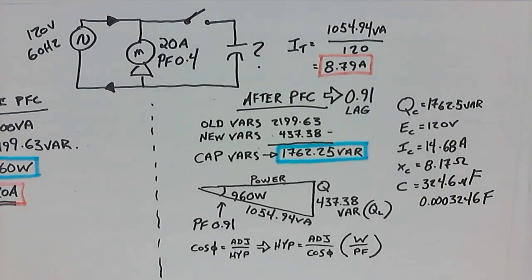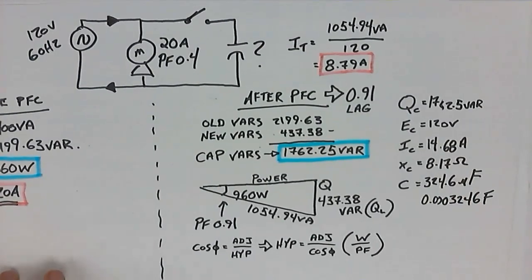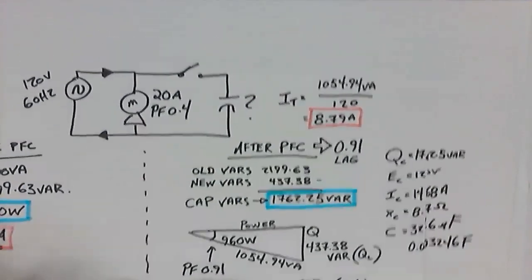So that is our full power factor correction calculation. Try out some of the handouts that I have provided within the course structure, and take a look at how that current value changes depending on how large a capacitor we put in there.